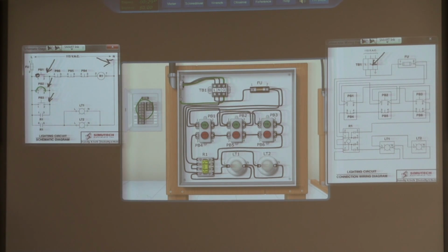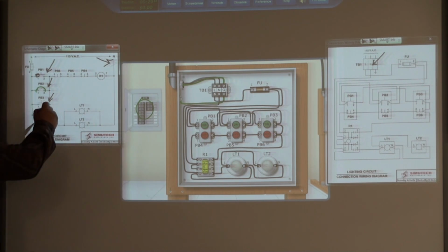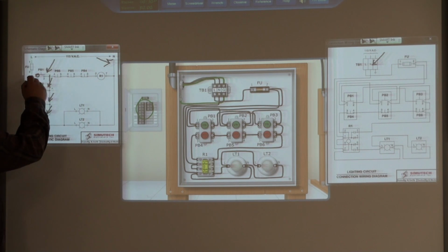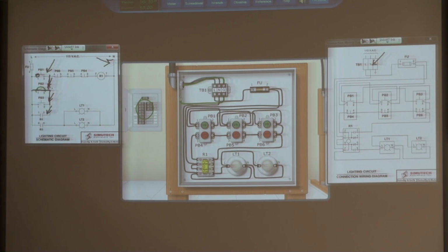And if we're not pressing a button and we've got 115 volts across the switches, then it could be this guy is welded shut, but it could also be a shorted switch. And if you took your voltmeter measurements, pin 1, pin 2 on PB2, and there was no change of potential with it open, that would tell you it was shorted, right? Well, you're not going to have a change of potential simply because this guy's supplying it here. Now, if you measure from pin 1 to pin 2, the 115 that's coming through this welded switch is being provided right here and right here. So it's still there.